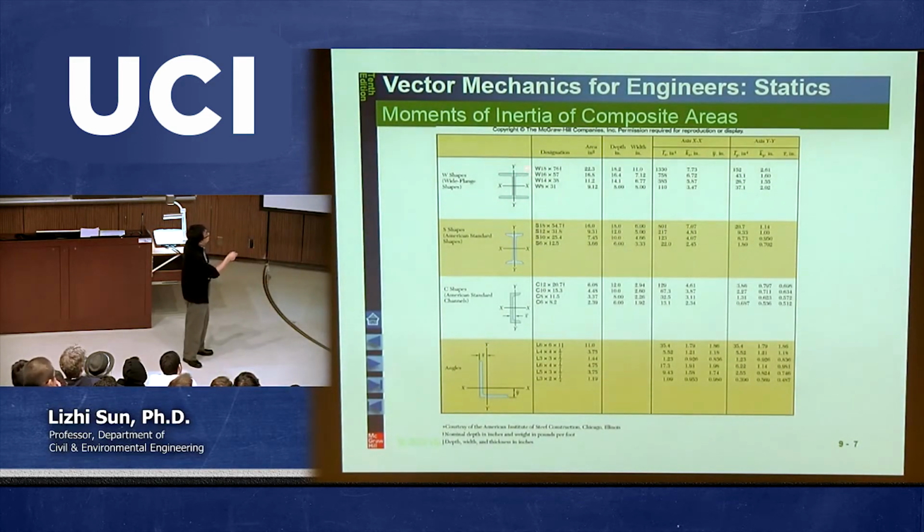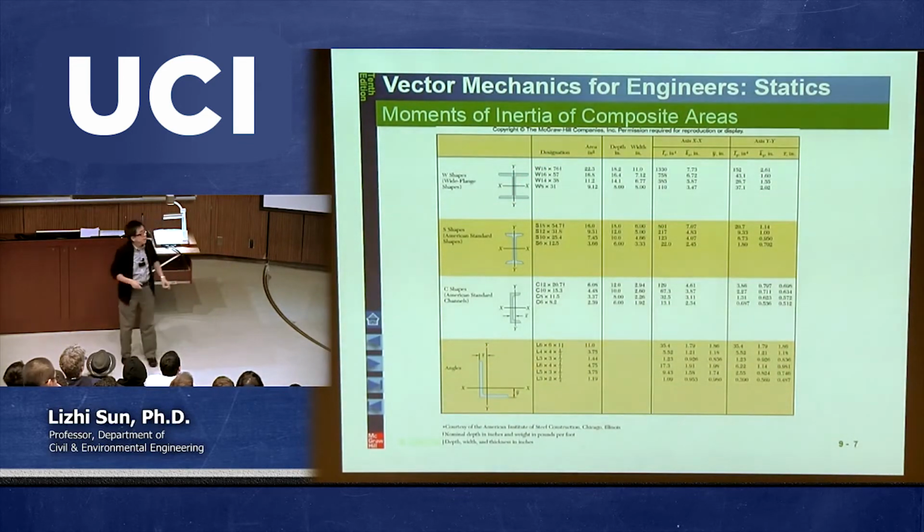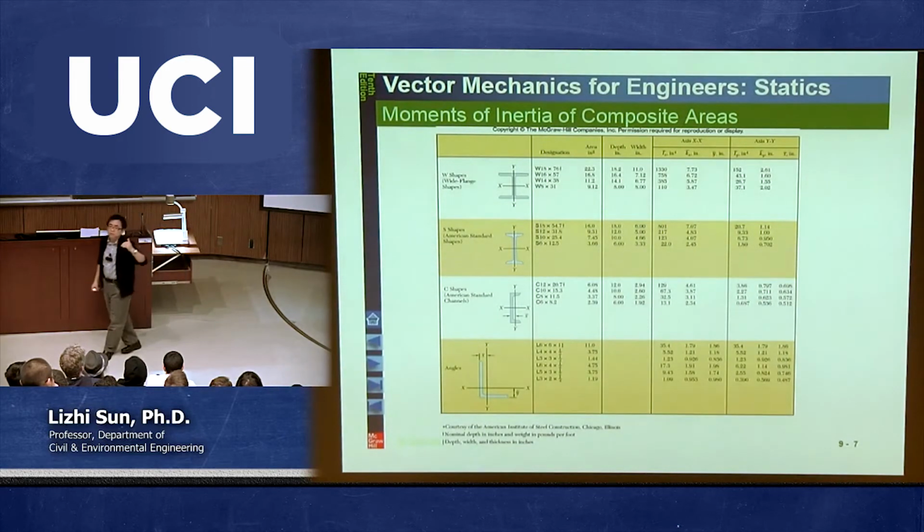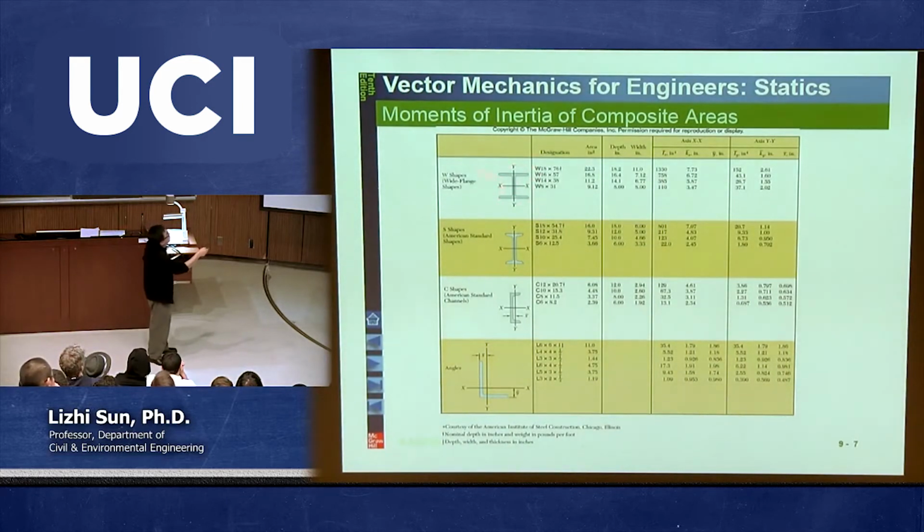It's because this one can give you maybe 50% of the moment of inertia of the rectangular shape. But the material you are going to use, compared with a full bulky rectangular cross-section, is completely different, because the cost is basically proportional to the material put in. So with this, you use much less material. In other words, you have a lower cost. However, the rigidity, or the moment of inertia, may still be comparable with the moment of inertia of the overall rectangular shape.